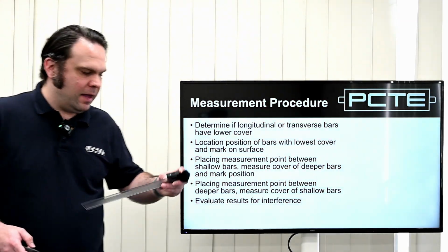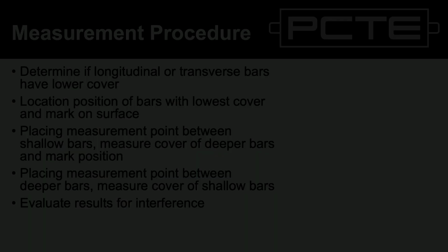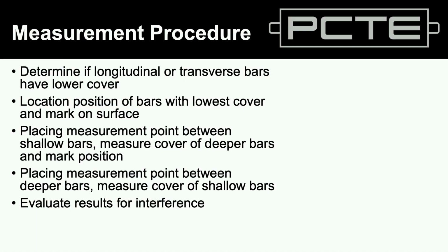So, how should we use a cover meter? This is a process to take an accurate depth of bar. Because if we just take the cover meter, see that it's got a number on the front, drop it on the surface of the concrete and go job done, that number won't be accurate. You're simply unlikely to place it in a position which is correctly oriented.